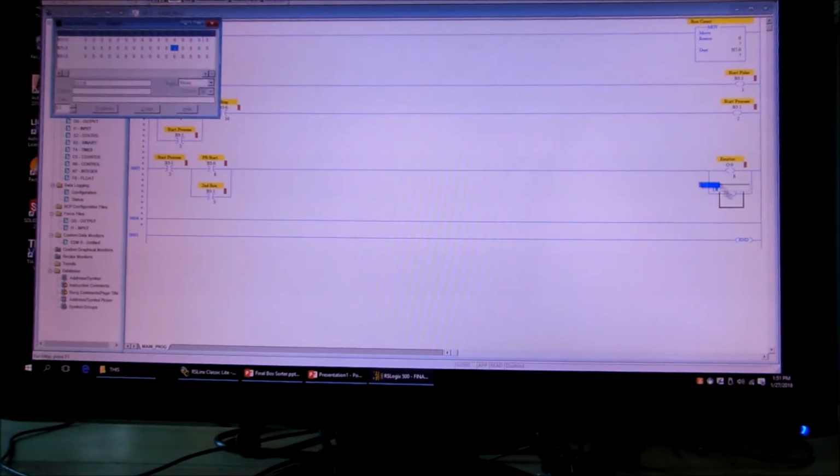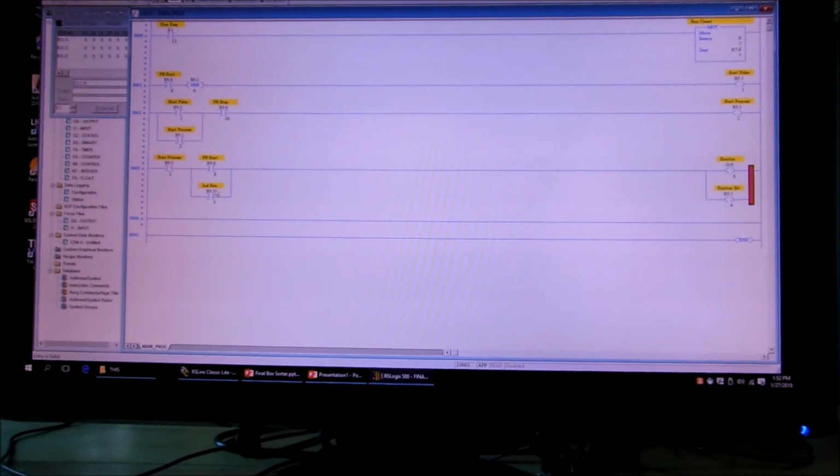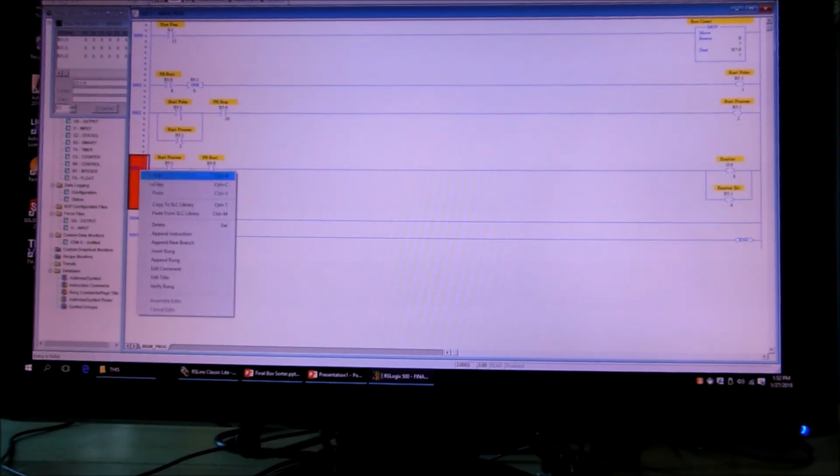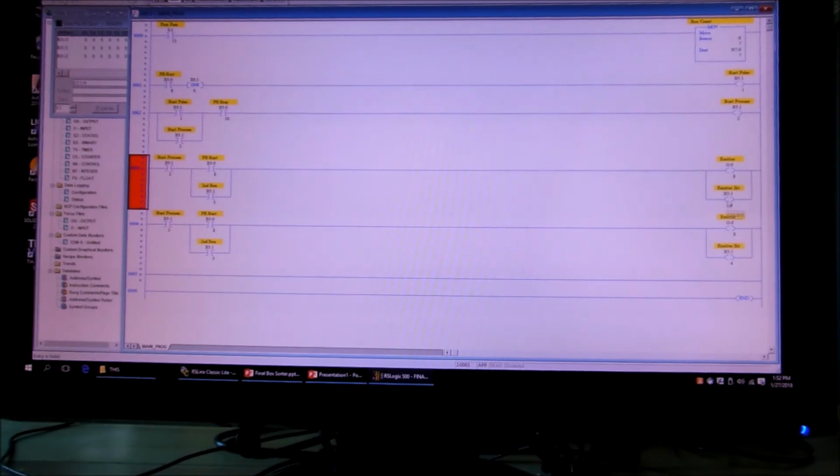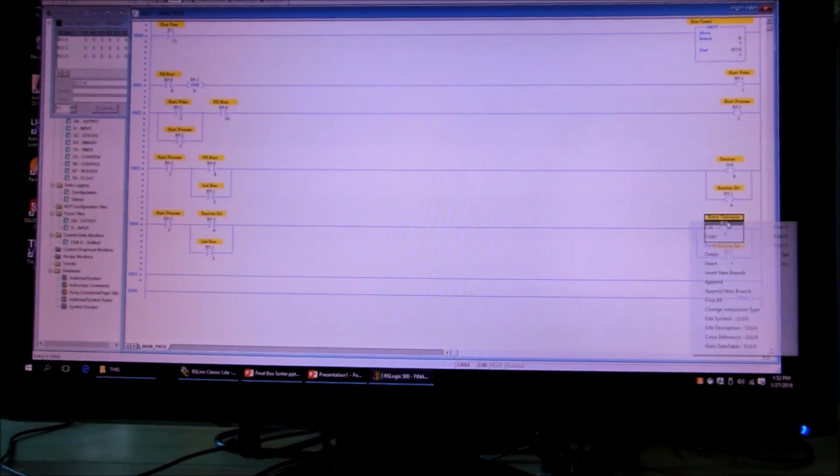So we're going to make that 4. And then here, you can just copy this and paste it so we have our basic setup. We're going to put our emitter bit down here, and this will be our conveyor entry, so we just need to change that to bit 0, which is the conveyor entry bit.